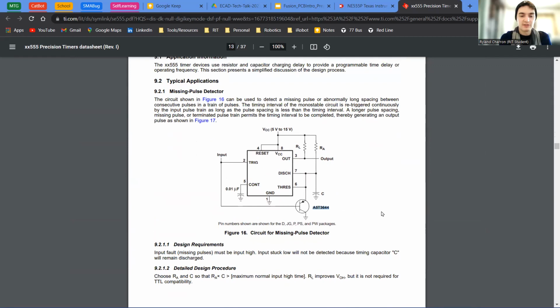Finding the transistor can sometimes be a little challenging. It's nice that it gives us one. However, I looked into it and this guy doesn't exist anymore. It's not sold on DigiKey, it's out of stock, it's not active. So we would have to find a new one. I already went through all that and did that for you. It's just another PNP transistor that works at the logic levels we're using. It's not super exciting.